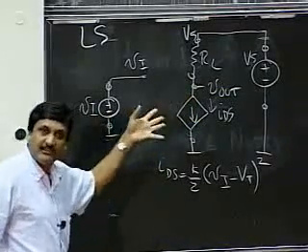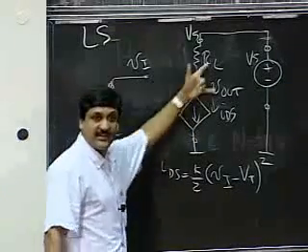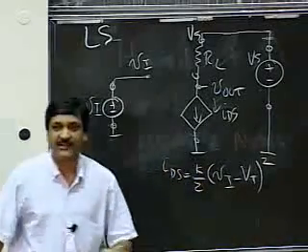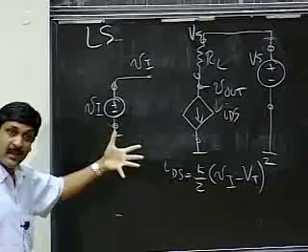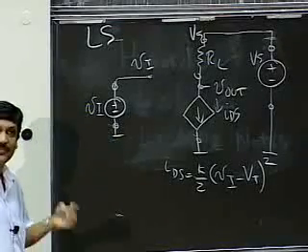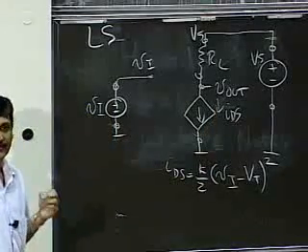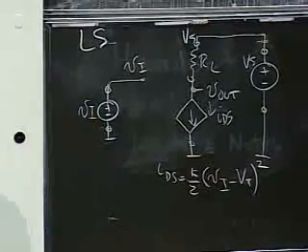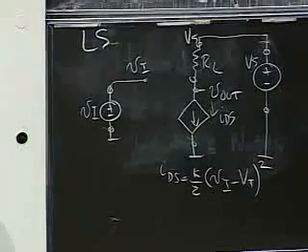By their nature, the small signal models are all going to be linear. So what I'm going to be left with is a linear circuit with simple linear circuit elements. And then once I have a linear circuit, I should be able to analyze it using methods 1, 2, and 3: superposition, Thevenin, node method, and so on. And certainly the intuitive methods like superposition and Thevenin make life a lot easier for me with linear models, and thereby get the function that I'm looking for very quickly. So again, my claim is that I can replace each of these large signal models by just small signal equivalents, and then just analyze the resultant circuit. And I claim that I should be able to get the same answer.